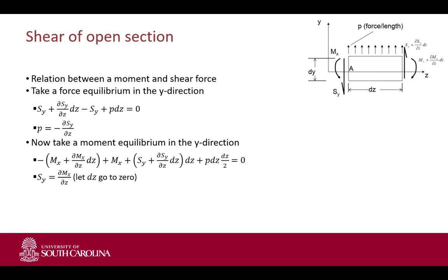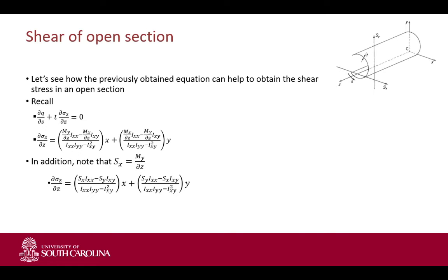That's what we did. And once we did that, we could reintroduce our bending stress equation, and we could take the variation with Z. And we noticed that the only thing that can vary with Z are actually the applied moments. The cross-sectional components like the moment of inertia cannot vary, so those remain constant. And we realized that the variation of direct stresses with Z equals the variation of the moments and the other terms.